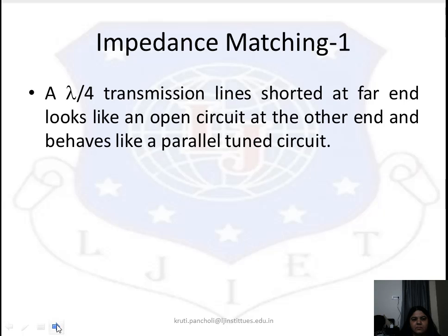A lambda by 4 transmission line shorted at the far end looks like an open circuit at the other end and behaves like a parallel tuned circuit.